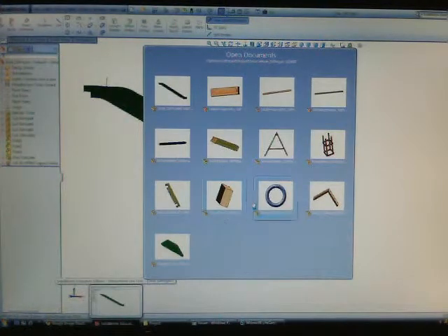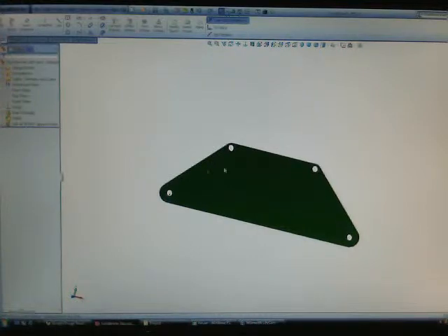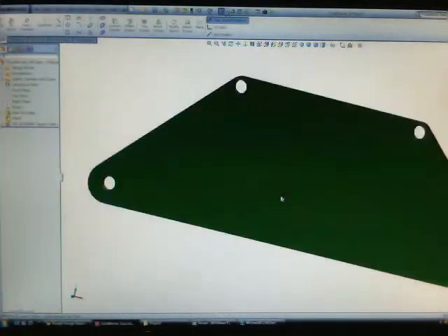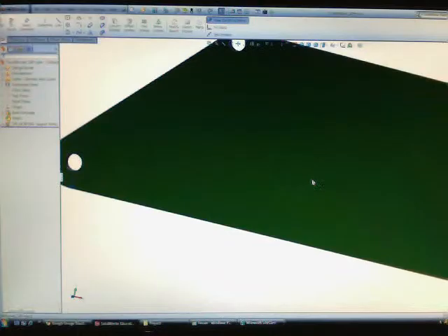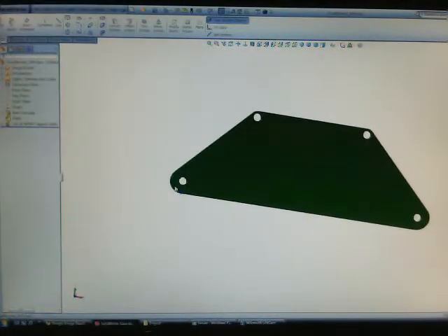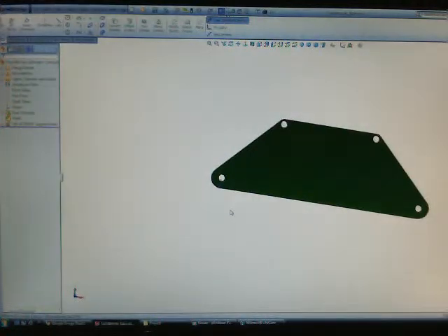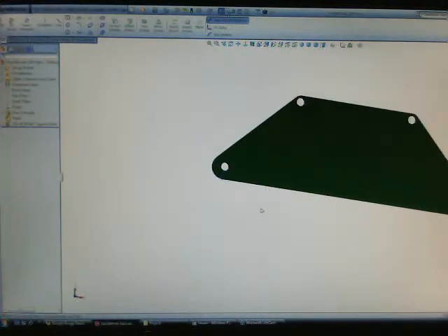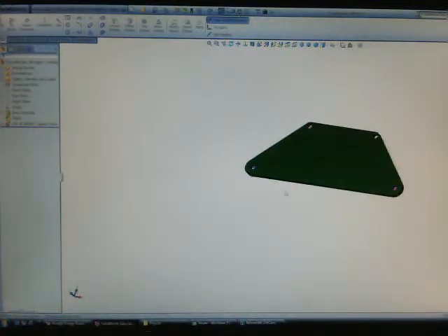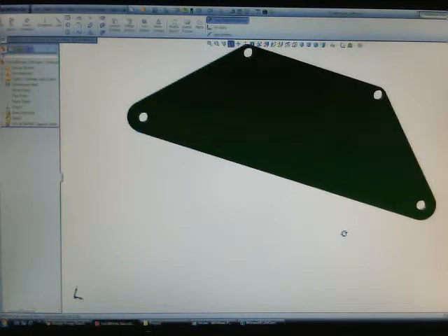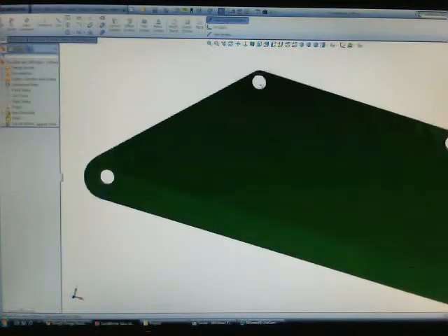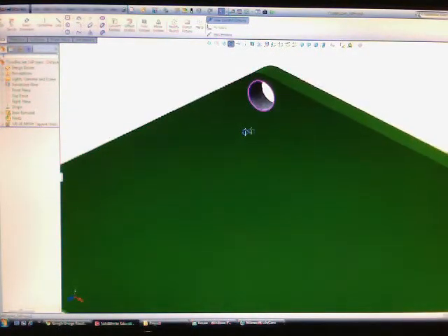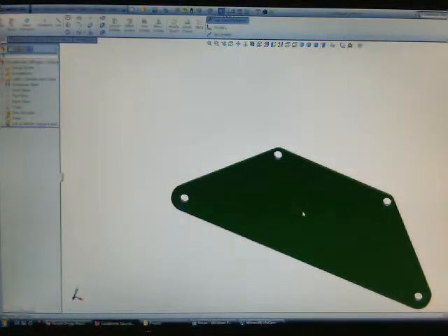Also, for this project, I was supposed to design the different types of brackets that were going to be holding the frames of the house. This is a truss bracket that is going to be used to hold the 4x4 beams for the monkey bars and for the swings. It's just a simple truss bracket created using the strut and fillet features in SolidWorks. This truss bracket is going to be mounted on the frame using 3/8 diameter bolts, and it's made of galvanized steel.